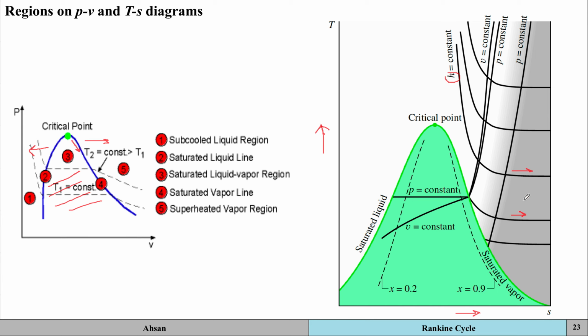And this is being shown in this shaded region over here. So for these states where this region is being shown as a shaded area, what this shows you is that enthalpy is a function of temperature only. So you can just look at the temperature within this region, and across the temperature in these tables, let's say, you can find out what the enthalpy is.